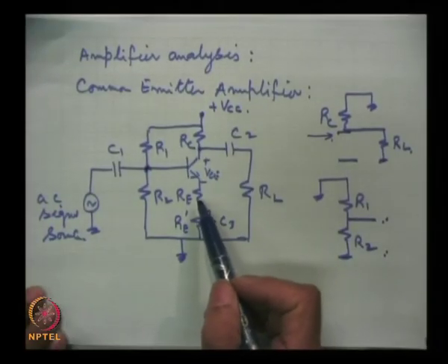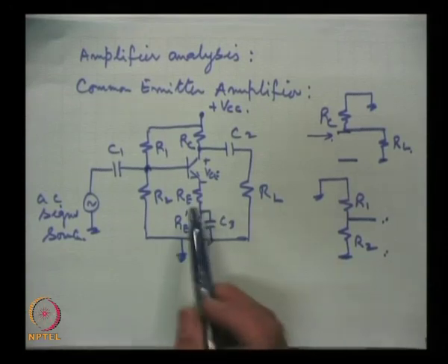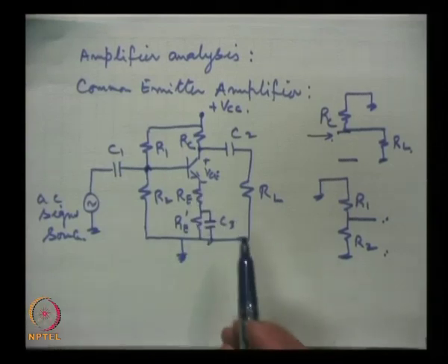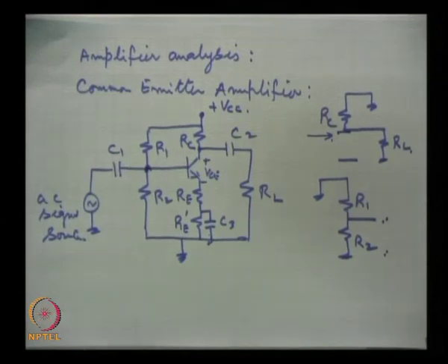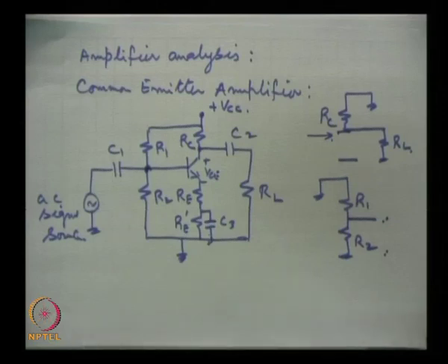The designers will make the circuit from where we started, in which one resistance is maintained in the circuit and one part is bypassed. This will be the best compromise. So, AV will not be as low as in the case of no bypass, and it will not be unstable because of the effect of the dynamic resistance.